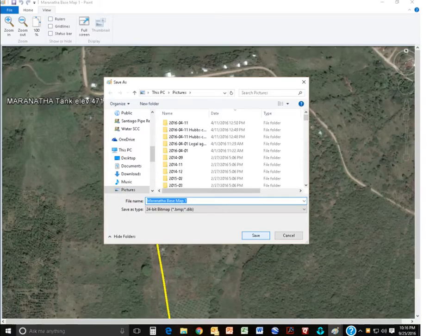Now, to get that Google Earth file as a bitmap, I open that image that I saved in Paint, and in Paint you can save as a bitmap. So it's the same picture, only difference is its save type is bitmap. Click Save on that, store it in a convenient place where you can find it, because the only thing EPANET will take is a bitmap.